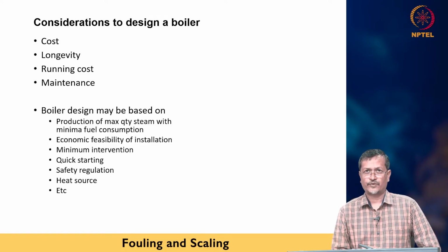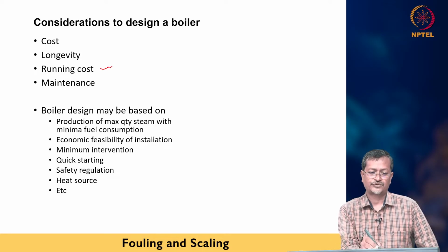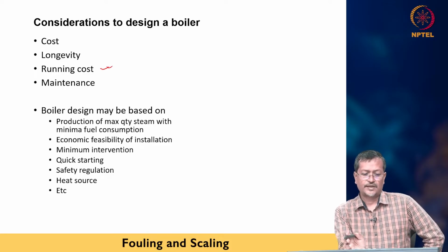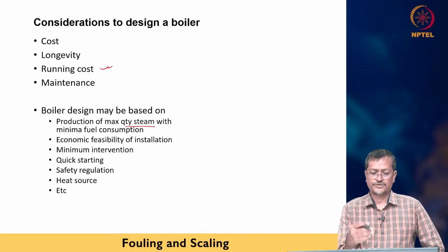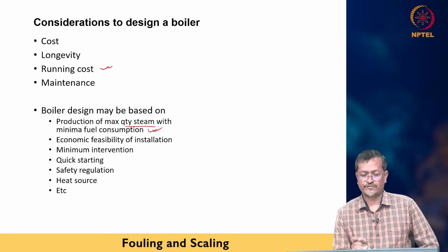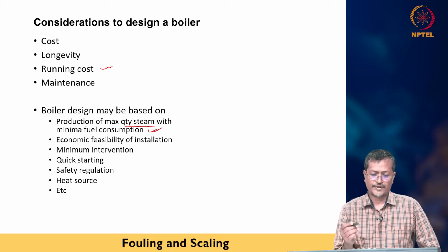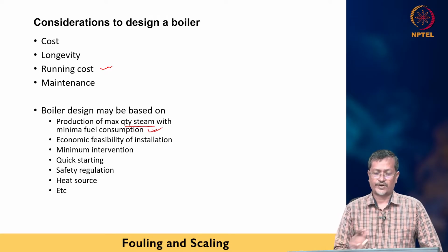Whenever you are designing a boiler, you have to consider the cost, longevity, how long it will be running, and the running cost. You should not have too much maintenance also. Boiler design may be based on production of the maximum quantity of steam with minimum fuel consumption. So performance is very important, along with economic feasibility of installation, minimum intervention, quick starting, safety regulation, heat source, and many other reasons before designing or installing a boiler.